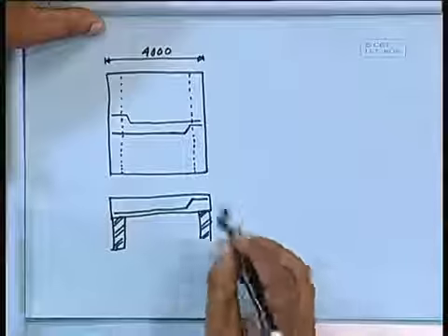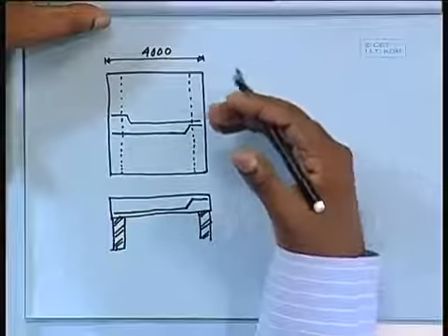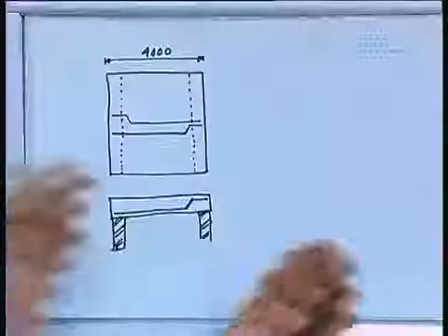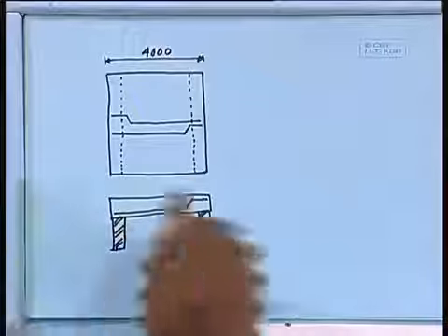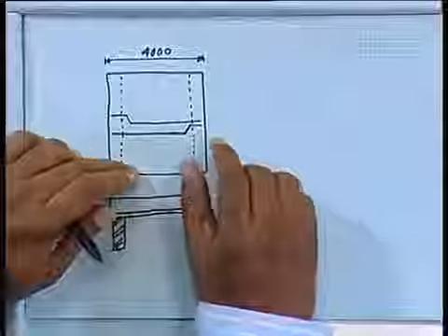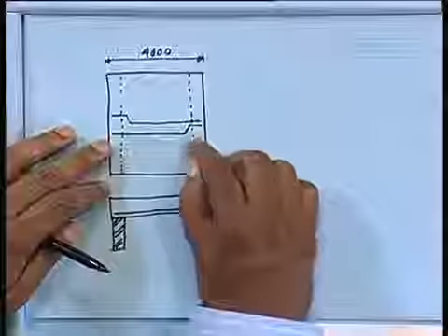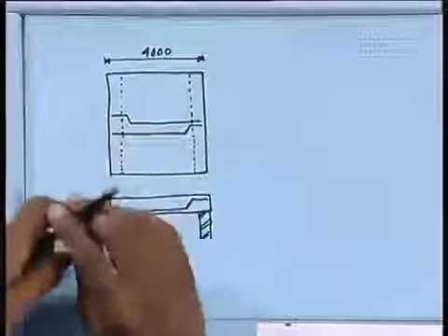That means alternate. So, the bars will be same, only thing one will be placed this side, another one will be placed other side. So, it will be cranked in one side only. At the construction site, they will crank in one side, but they will place alternate way.